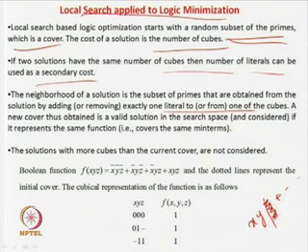So, if you just remove this, then it may become an invalid function also. So, if it becomes an invalid function, then you have to throw it away, but if it remains a valid solution, then you can think about the cost. Obviously the cost has reduced because you have removed one literal. Okay, and that is what we are minimizing.